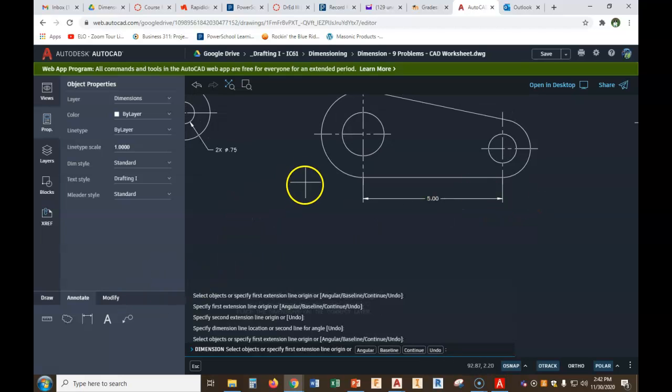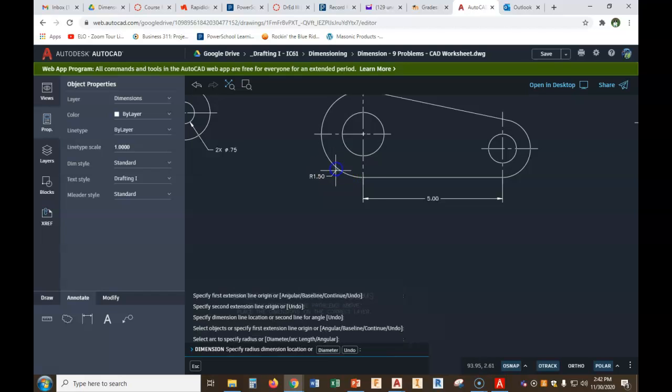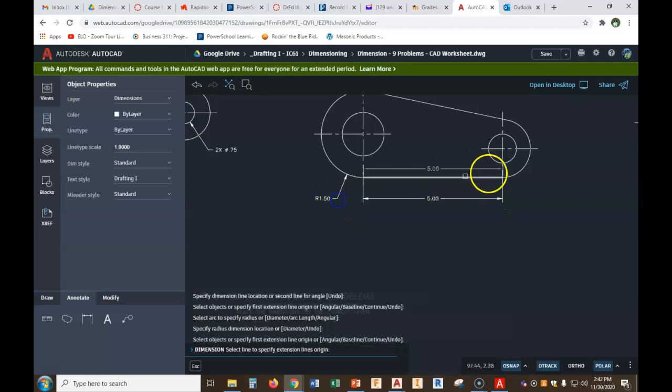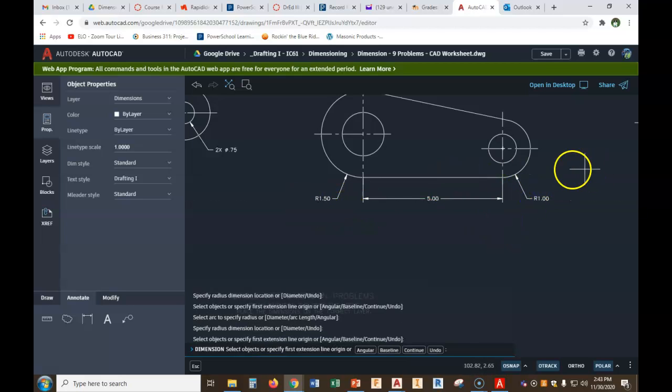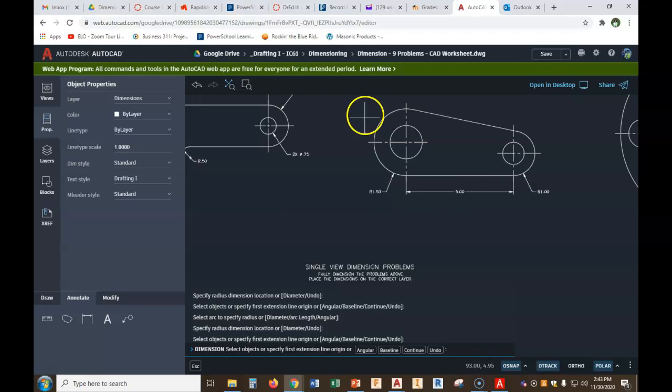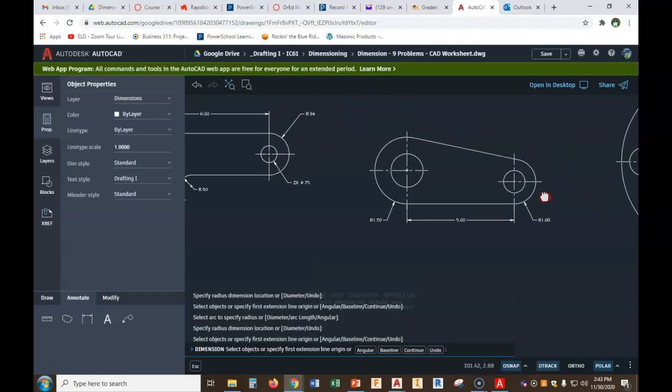Okay, now I'm still in dimension. Hover, find radius. There it is. Click. Now drag it down here, find an empty spot, and come over here a little bit, right about there. Same thing here. Hover, 1 inch, get it to take. So click, now drag down, hover to your arrow, drag out, and click. Add those three things together. That's overall width. It's also overall height here, okay?